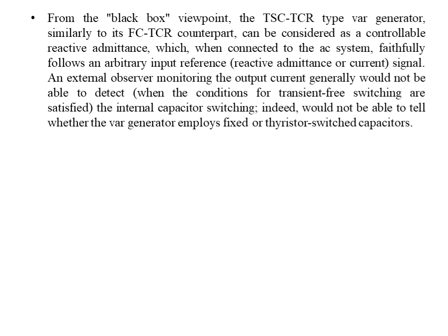From the black box viewpoint, the TSC-TCR type var generator, similarly to its FC-TCR counterpart, can be considered as a controllable reactive admittance, which when connected to the AC system faithfully follows an arbitrary input reference reactive admittance or current signal.